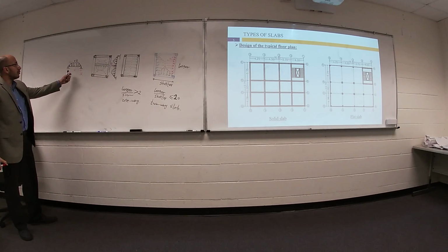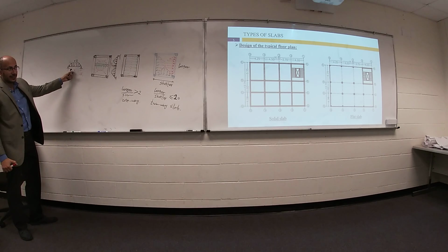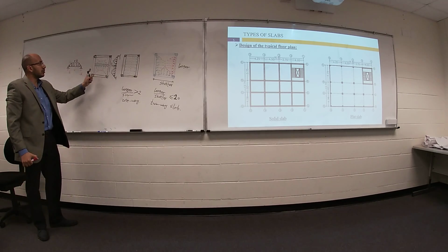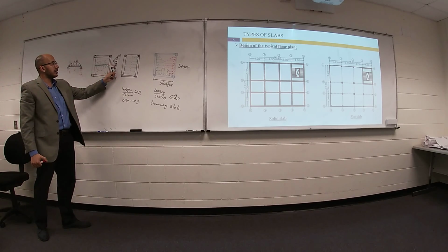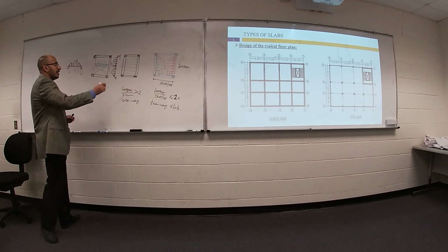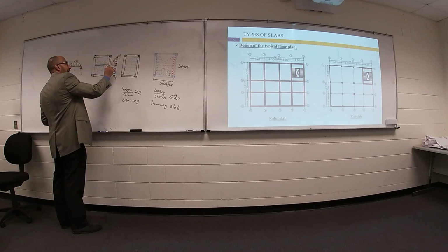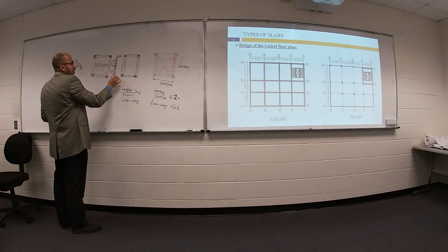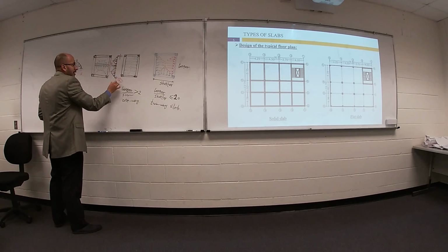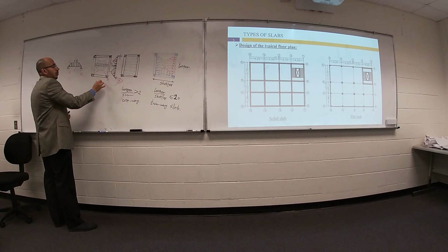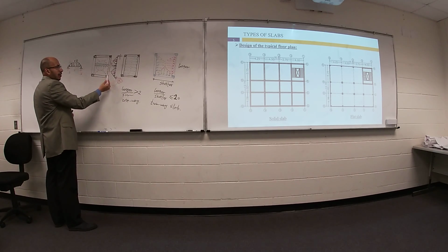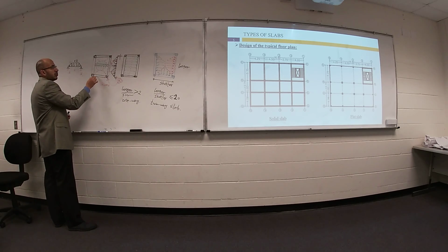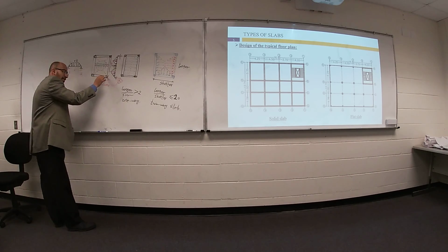This is the reason why you need to solve this beam first, before solving this beam, because you need this reaction to be a concentrated load beside this triangle and this triangle. If you decided to get this reaction R, this reaction is a reaction on your column. If you would like to design your column, you have to solve this beam and this beam also, because you have another reaction from this beam on the same column.